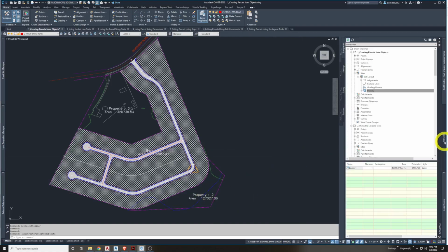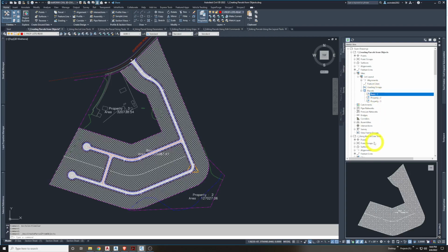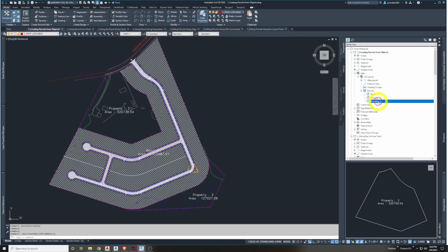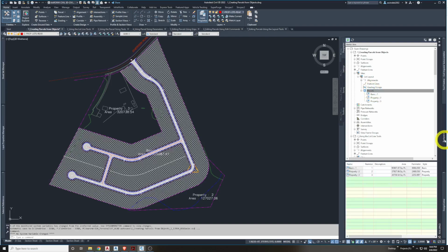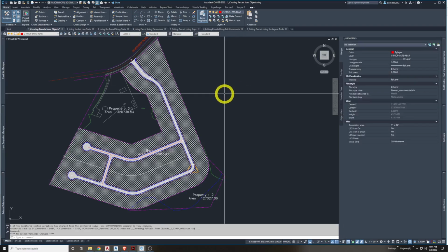We'll go back to our prospector tab within tool space and take a look. See this weirdness here. We'll do refresh. And now we have a few parcels. Okay. Now we're going to add some more stuff. Well, it wants us to click on the basic one parcel now. Just click this to get a preview of it. Okay. We can kind of get previews of these too. And we're going to add some more parcel data here.